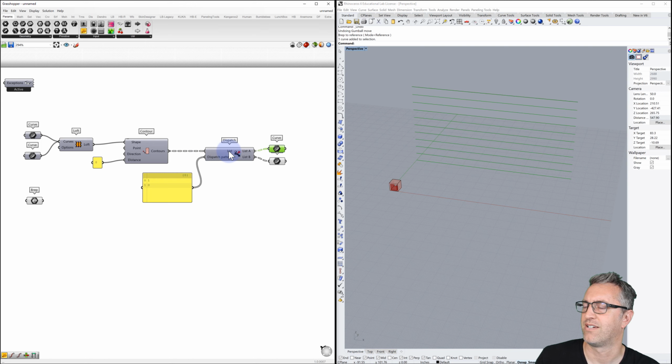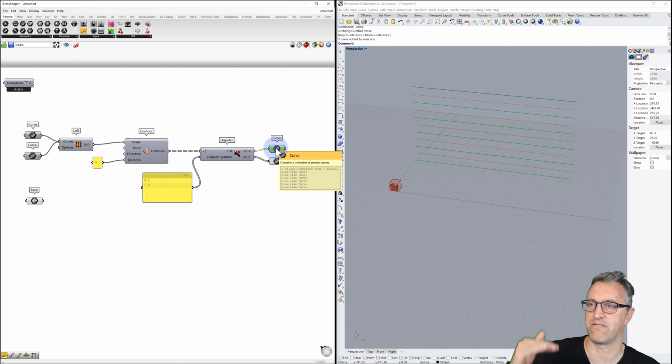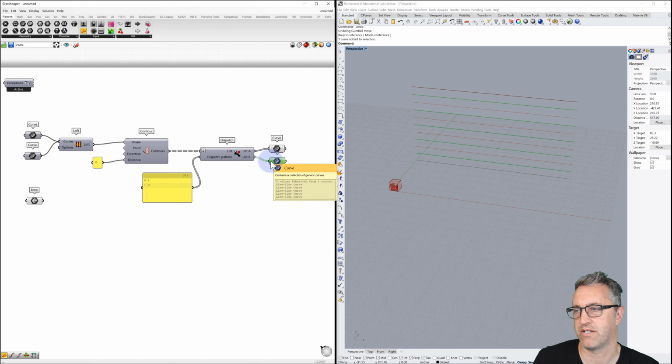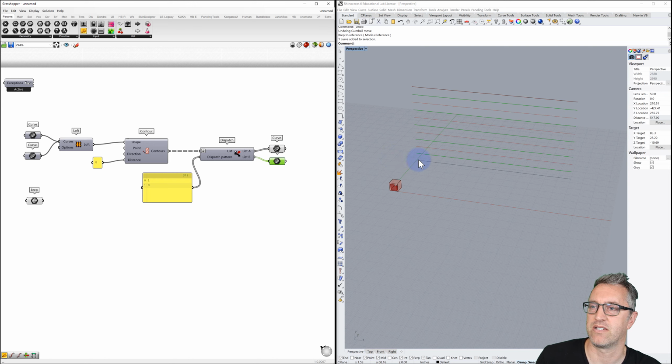Here's what I need to do. The problem is that I didn't flatten the contour lines. So now we can see as we select list A, that's this row, this set of every other curve, and then list B is the other set of curves. It's basically 0, 1, 2, and so it's even and then odd. And this is a simple way to set some of our Boolean patterns, a 1 or a 0, and I like to do that with a list. It's easy enough to include those. So now we have two sets of curves, even and odd,